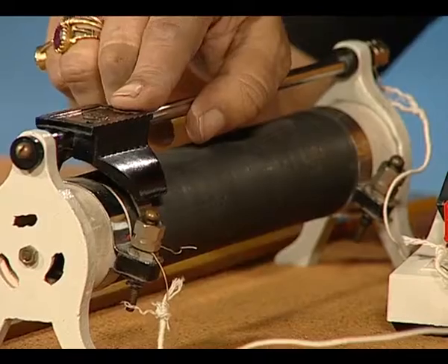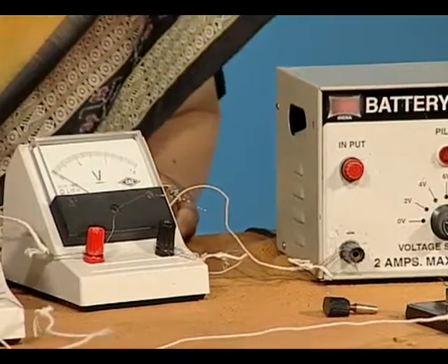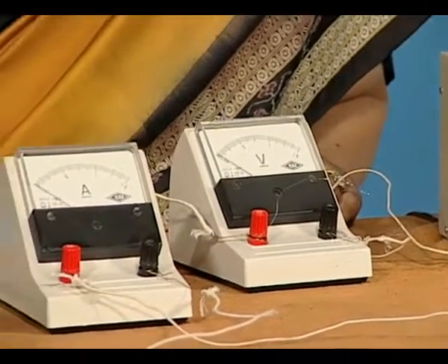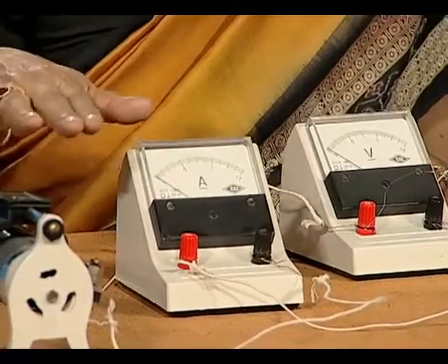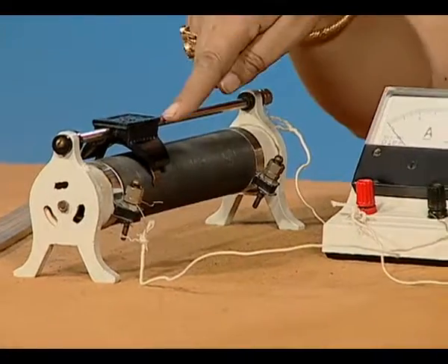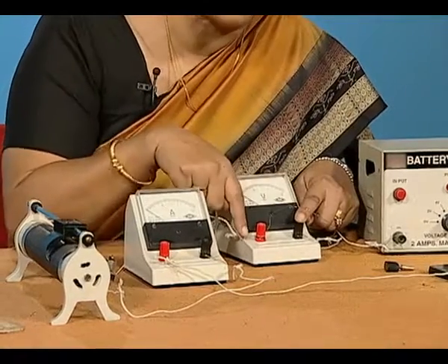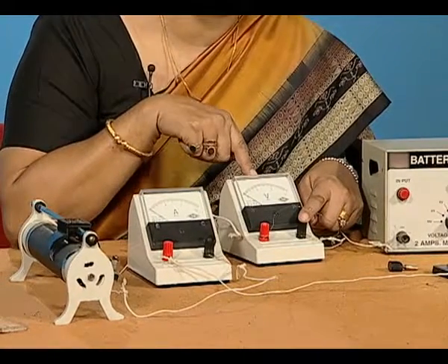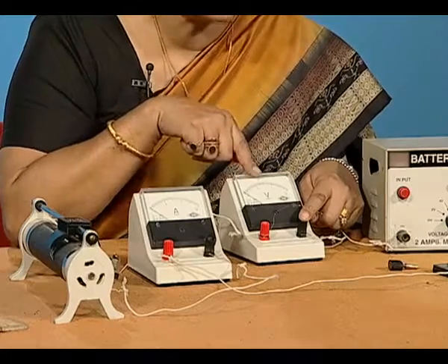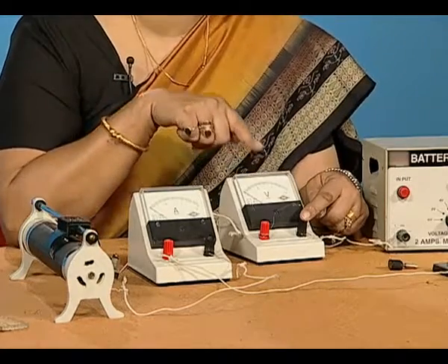This is the variable resistance, and it is going to allow us to change the value of current in the entire circuit. The current change here will develop different potential difference across this wire, which can be measured in this connection. So, let us do this experiment and set up an observation table.